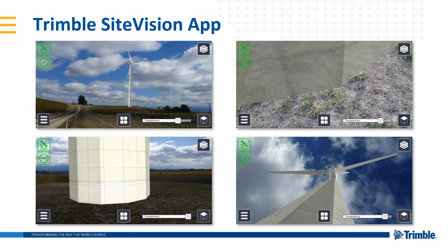And I've demoed that several different times for the surveyors out there, where we are staking out an IFC model with an SX10, for example, and then we load the same model in the same coordinate system into a SiteVision device. Standing next to the survey rod, you look at the tip of the rod through the SiteVision system, and when the tip of the rod is on the corner of the foundation, for example, or whatever component of the model it might be, the view through SiteVision is within 2-3 centimeters of what's being set out. So it's a very, very accurate system.